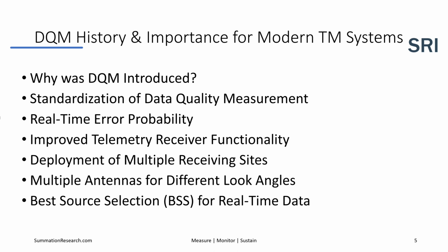This is great for link testing, but how would a range know how well a link is performing at any given time when Project X is flying in a test range? Typically, test articles transmit the same telemetry signal on two different polarizations.